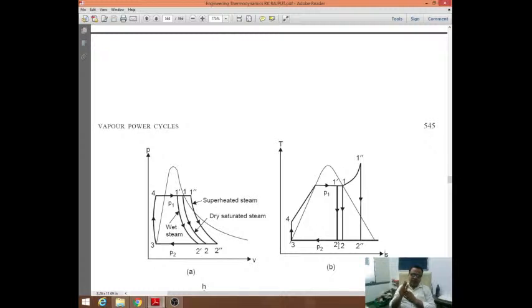For everything, if there are advantages, then there are some limitations or disadvantages associated with that. At one end we are trying to achieve the superheated steam resulting in reduction of turbine erosion. At the second point, we need to design the condenser with larger surface area so that it can be used for more rejection of heat, and that will of course increase the requirement of water. So a judicious decision has to be taken.